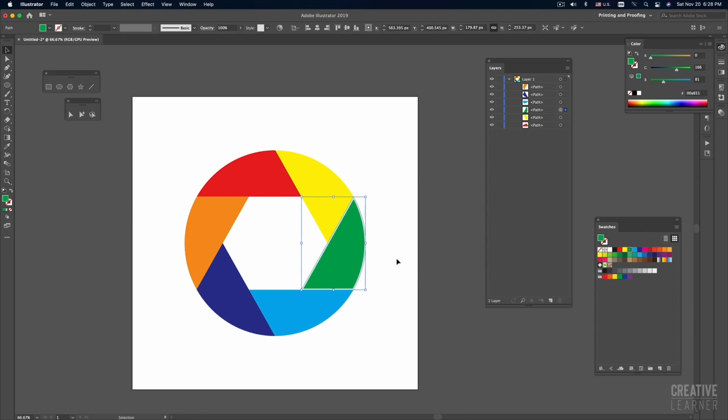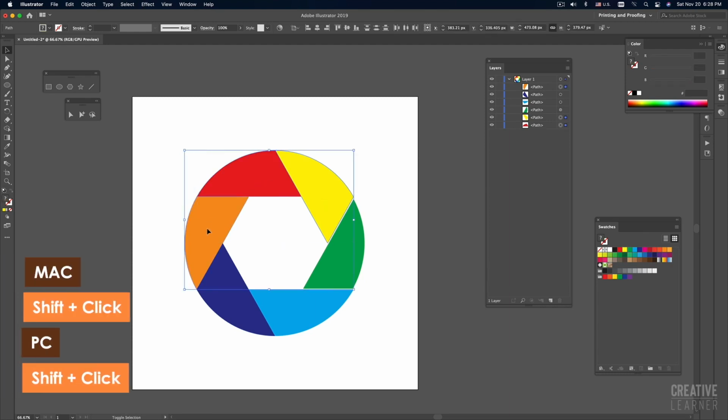So it is like we are creating a gap. We need to do the yellow, red, and all the shapes all around, the same thing. We need 3 pixels going inside. To do that, I can simply select the rest of the object shapes. You can click and drag over whatever area you can select, or if not, hold down your shift key on your keyboard and then click and select all the objects. Do not let go of your shift key. After that, you have selected all the rest of the shapes.